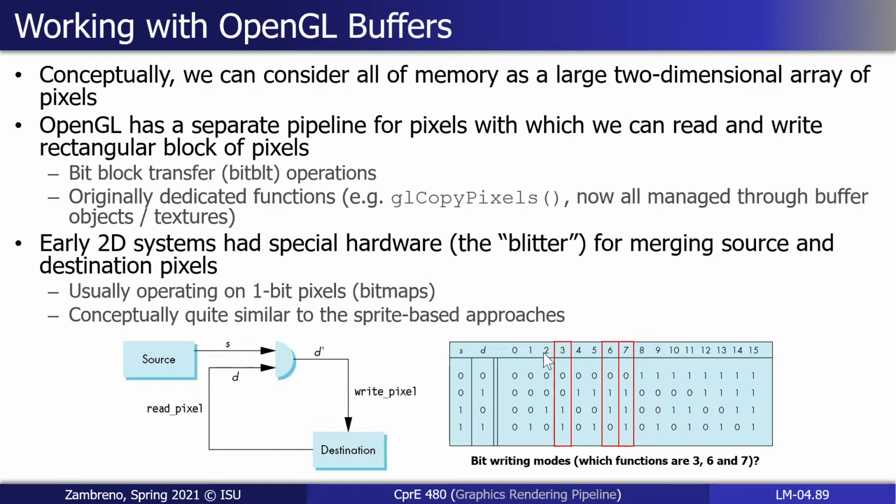And this is our programmable truth table. Think of it like a LUT in our FPGA if we want to. And we would literally have our LUT have one of these functions, or think of it like a CPRE 281 truth table where you do logic minimization and things like that. But your blitter hardware would be reprogrammed at any given time with one of these 16 functions.